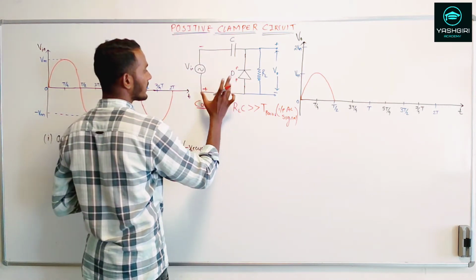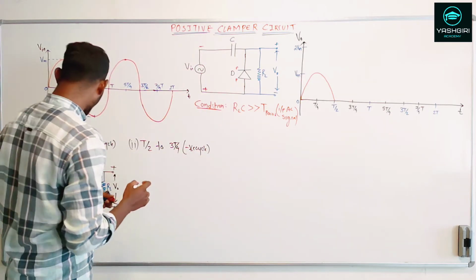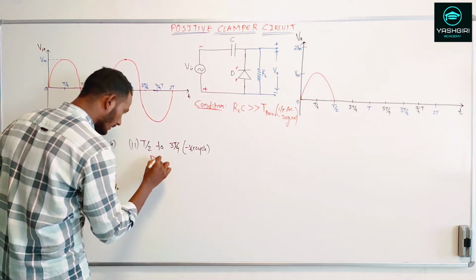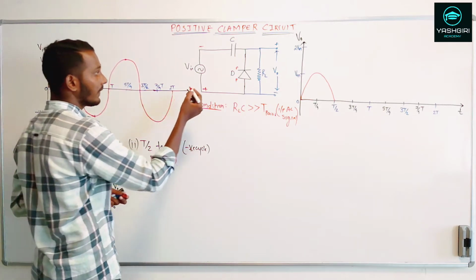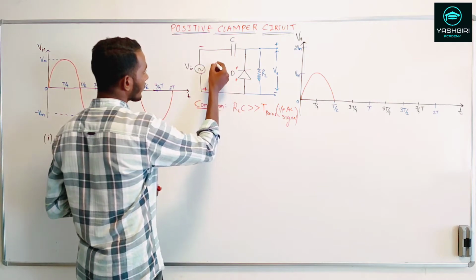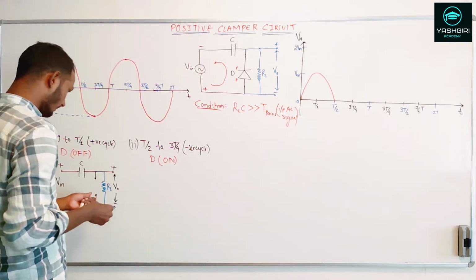Now if you see, this P is connected to the plus, that means the diode can conduct. So I can say the diode D is in on mode. When the diode conducts, the current will start flowing in this circuit. All right, so let me show the equivalent.